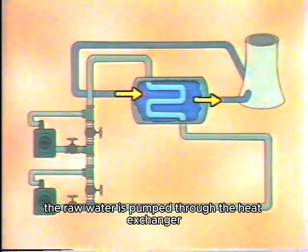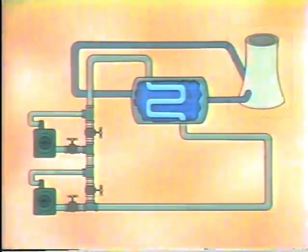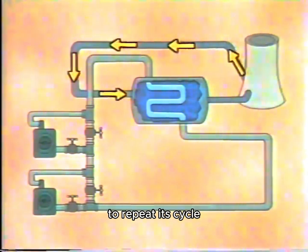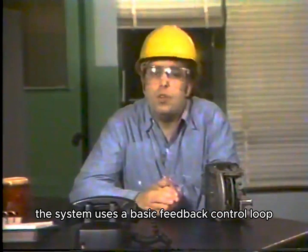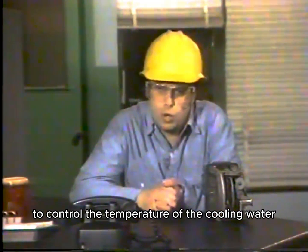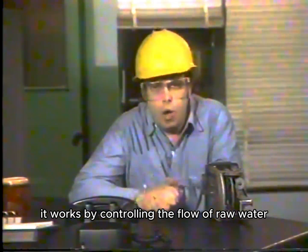The raw water is pumped through the heat exchanger to a cooling tower where it is cooled. After cooling, it is pumped back to the heat exchanger to repeat its cycle. The system uses a basic feedback control loop to control the temperature of the cooling water. It works by controlling the flow of raw water.